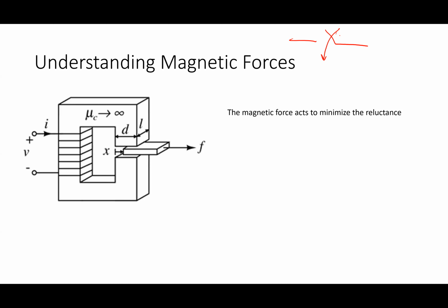Or sometimes you have valves that work like this. All right, so the thing that I gave you in problem 4 in the homework is what I call a solenoid valve. A solenoid valve is basically just a valve that has a coil like this. Basic electromagnetic motion: if I want to have one-dimensional motion like this, it's a very simple way to make it happen. All right, and I want to figure out how much force this guy can produce.